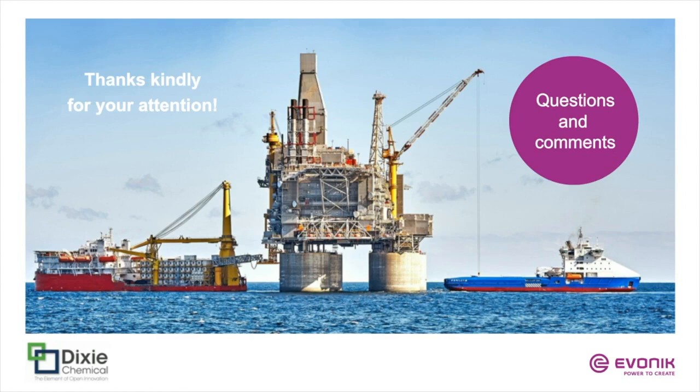I mean, just to emphasize, yeah, you need a material that's cross-linked extensively enough to allow it to survive under the increased temperatures that the material will experience in deep ocean downhole temperature ranges. It's got to be able to support the column of water that's sitting over it, and then yeah, I think density also as well, simply because you need to be able to help a little bit with the buoyancy of these materials so that they aren't adding tremendous weight to the overall mass of the system that's being supported.